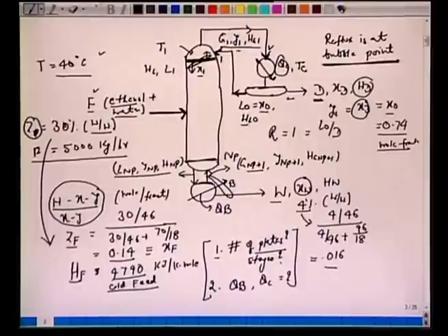All right. So what we do, we have mole fraction, everything is known. In fact, this feed is 5000 kg per hour. It's also important that we convert this feed to mole per hour. So this F is 5000 kg per hour. This can be converted into 5000 divided by the average molecular weight of this feed, to show that this would be 227 kilomole per hour.